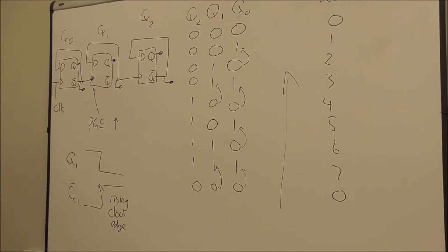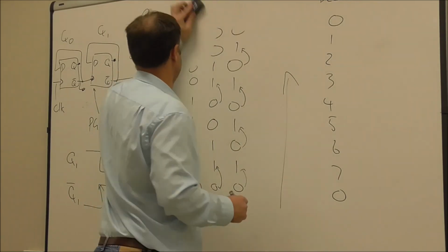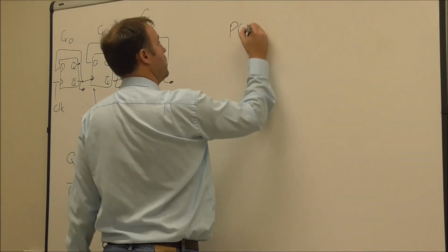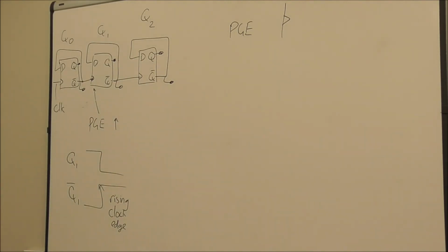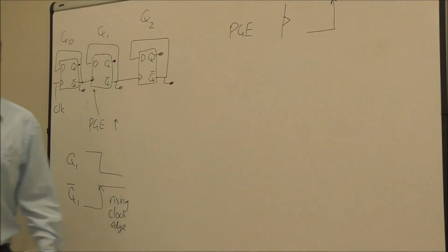Okay? So if you make one of those changes, you'll change it from an up to a down or a down to an up. The third way, and this isn't really preferable because you need to replace the whole chip, and it might not have the same pin out, so it's not particularly easy to do that. But you can change it so that it's not a positive going edge clocking chip. So a positive going edge has this symbol on your flip-flop or on whatever chip you've got. Okay? So this will mean it transitions when it sees that rising edge.